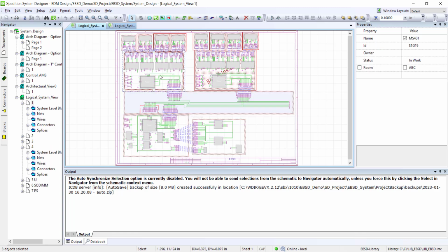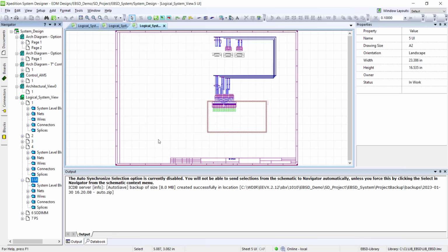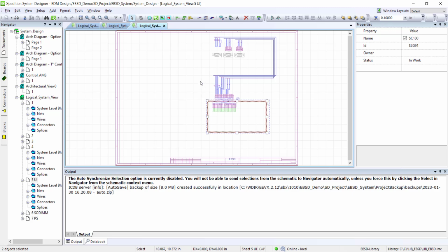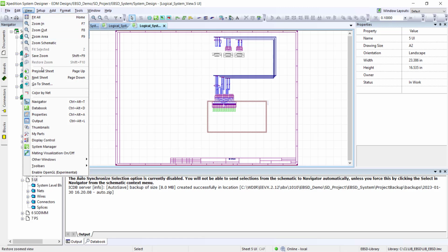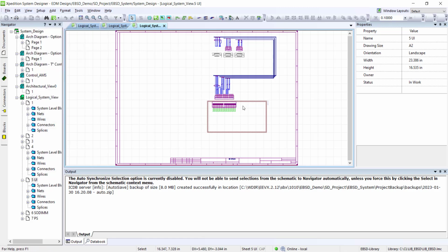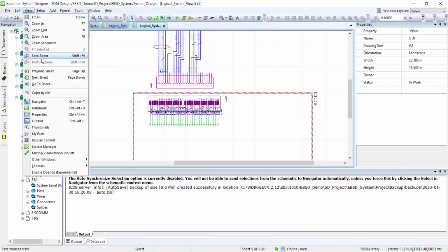Both of these views of the BP100 board do not need to include the entire board construction, but instead the logic specifically linking it to other pieces of the design. On sheet 5, one view of the SC100 board is shown along with its logical connection to the cable that we're going to be replacing. Using mating visualization, the designer can validate and observe pin pairing logic to eventually be used in the flex PCB design. This visualization tool can be toggled on and off.